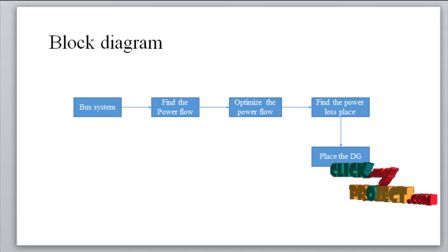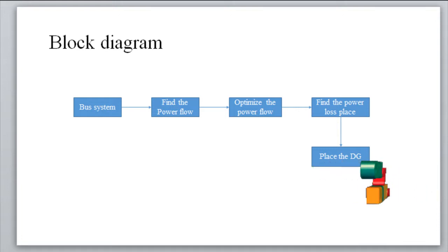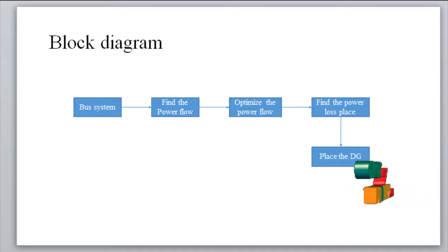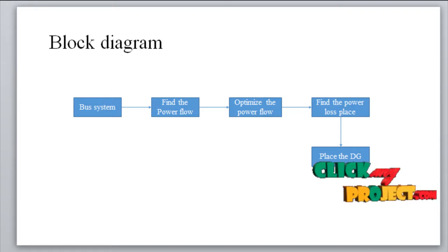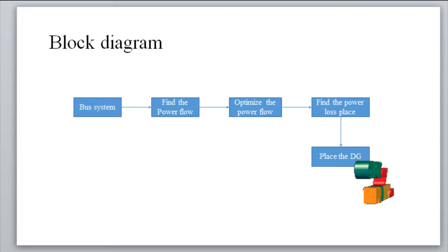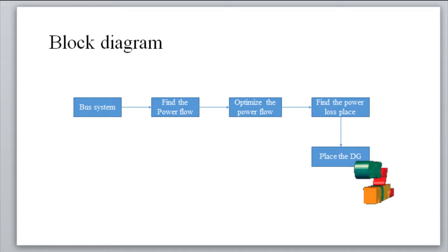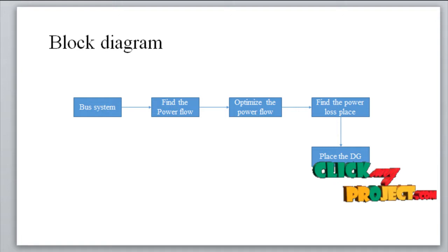In power flow, the most difficult and computational task is inverting the Jacobian matrix. In factorization, a full matrix is on the order of n cubed operations, meaning the amount of computation increases with the cube of the size of the problem. This amount of computation can be decreased substantially by recognizing the sparsity of the matrix and the Jacobian of the process. So this element of the optimization in demand response makes perfect sense.